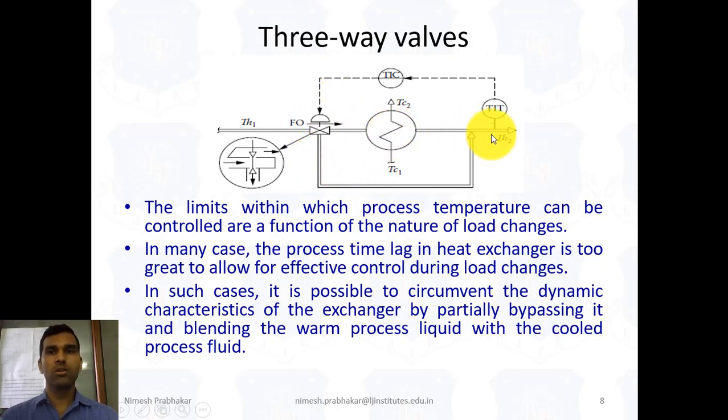So to control this temperature, the controller opens and closes this valve. That means it increases and decreases the inlet flow, or it also increases or decreases this bypass flow, and regulates the temperature of this outlet flow.